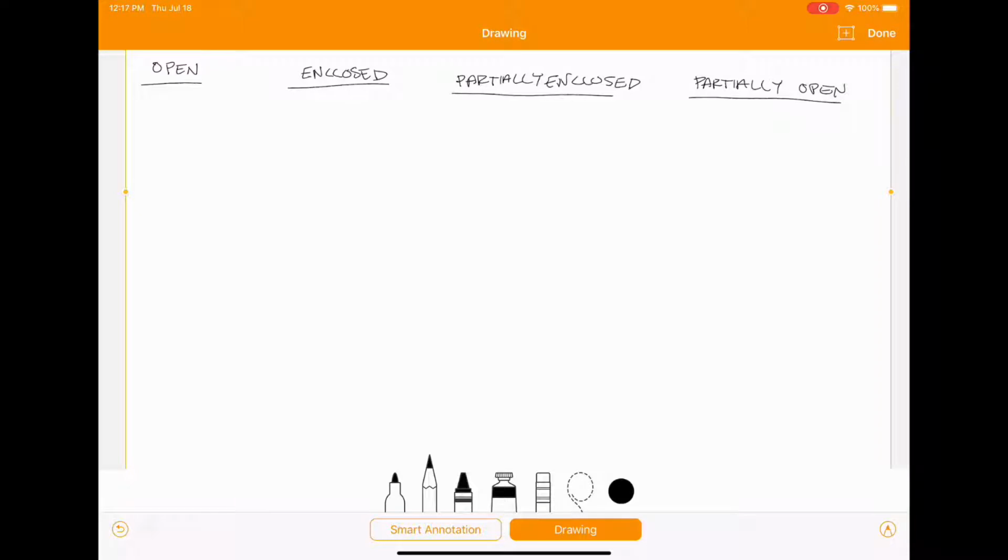And for it to be open, you've got to satisfy this equation, where A naught is going to be the areas of your openings on that wall, and AG is just the area of the wall, the gross area of the wall.